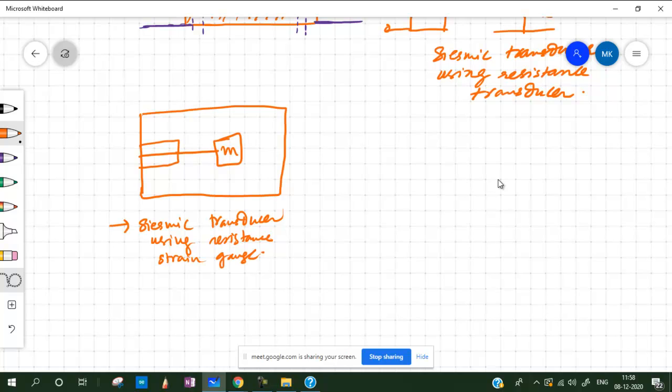Here, basically, we bring in a cantilever, a cantilever spring, for the spring action we need. It's not necessary to have just a coiled spring; you can have springs in this form also. So we have a cantilever spring. Maybe damping is provided in a different form. In this case it could be a viscous liquid, in which it is all suspended, for which we know the damping coefficient, and for spring action we are attaching it with the cantilever spring.